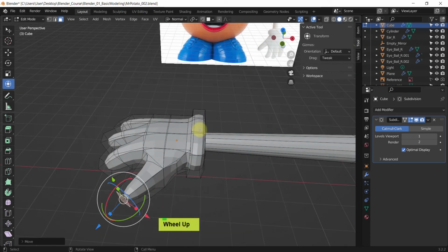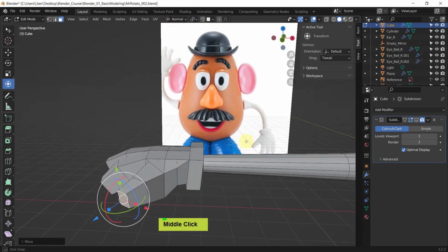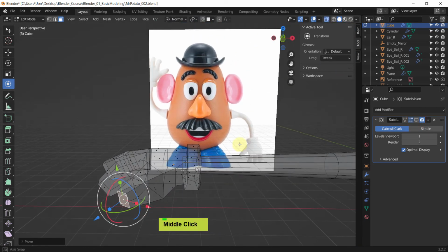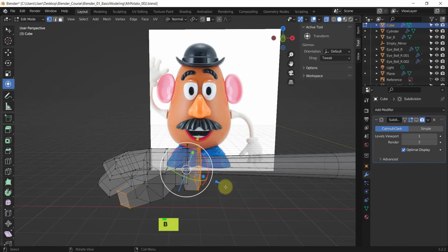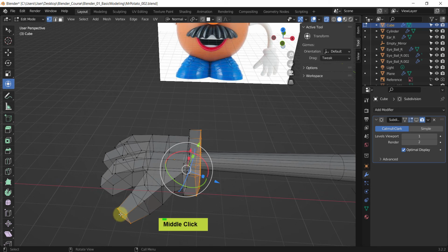This little cuff here should be a little bit wider, so let me just turn this off and select. Go to Alt Z see-through mode and select the points, vertices, and B, drag select these guys. I'm not sure about this section, okay, we definitely need to untick these.